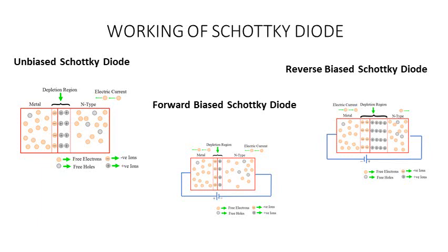So you look at the width of the depletion layer in the unbiased condition and compare it with that of the forward bias depletion region, you can find that this depletion width is reducing. When you connect it in a reverse bias, the width will start increasing. As the reverse bias keeps on increasing, the width increases until at a particular point the current flow stops. With an abnormal increase in the bias voltage, this depletion region will break down and the device will be damaged.